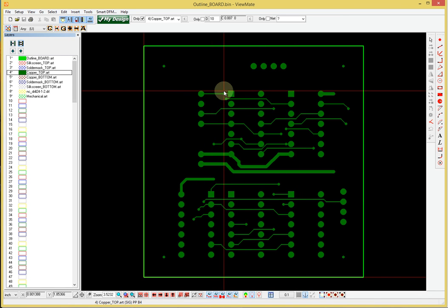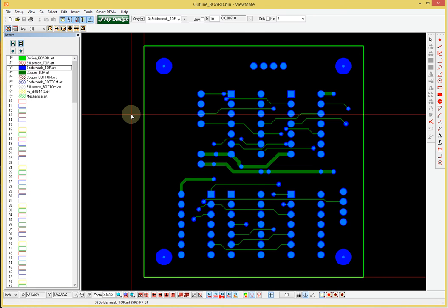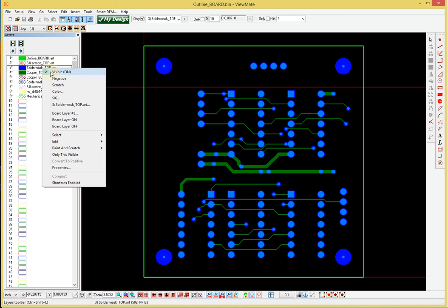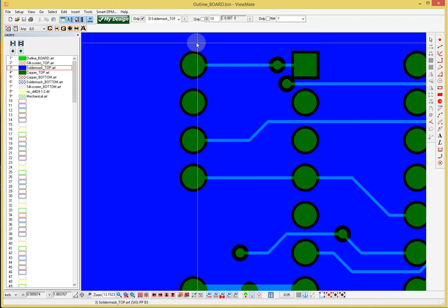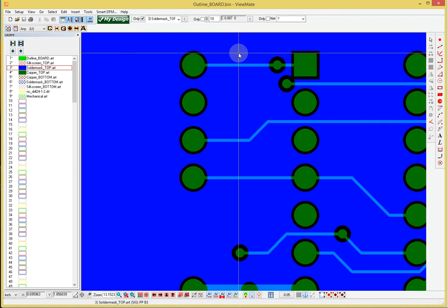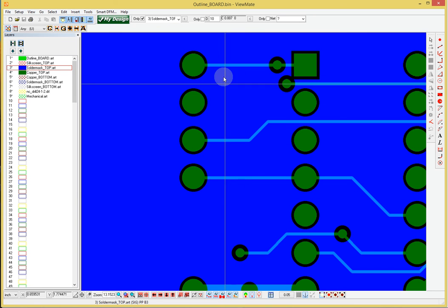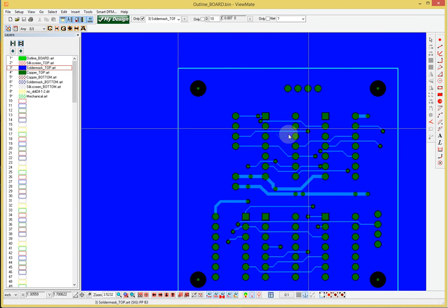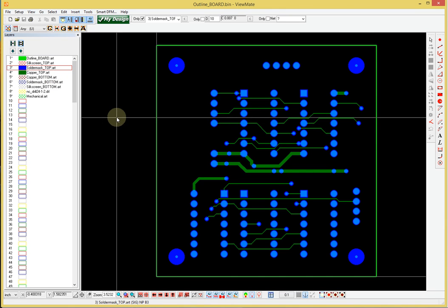Okay, on top of the copper, we usually protect it with another layer called a solder mask. To show you its function, I'm going to reverse this into a negative and really see that the solder mask is a thin layer of plastic or material that covers and protects your board and the traces of your board, and is only exposed at the points where we're going to make electrical connectivity with the components. The rest is just covered up. And that hurts my eyes, so I'm going to put it back onto positive.